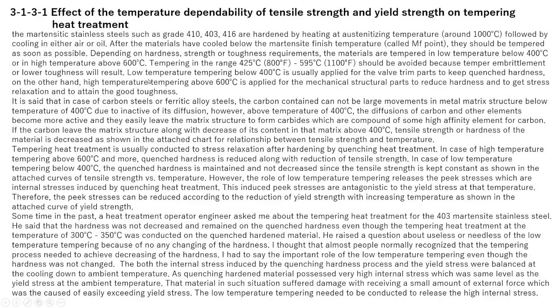Low temperature tempering below 400 degrees Celsius is usually applied for valve trim parts to keep the quenched hardness. On the other hand, high temperature tempering above 600 degrees Celsius is applied for mechanical structural parts to reduce hardness, to get stress relaxation, and to attain good toughness.